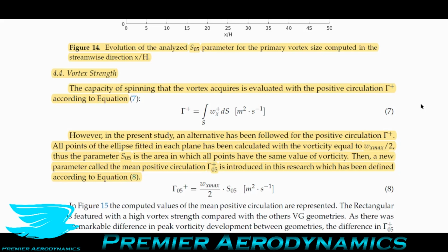So even though most of the vorticity is really contained within this region, there is still a lot of vorticity that isn't, and there's a lot of the vortex that is not. So the circulation calculations to get the strength of the vortex are not going to be accurate because you're missing out a bunch of the vortex. And even though you may assume that the vortex is well behaved, in that most of the vorticity occurs within this line that you have, it may not. It really depends on the situation, and you may be surprised sometimes.